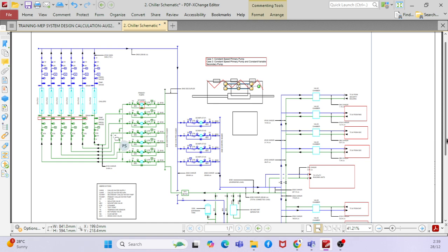Yeah. So then it will go to the chiller. That particular chiller will try to sense the flow, and whether the delta T can be maintained or not. If not, it will try to reduce the compressor speed to maintain the chiller flow rate and the chiller temperature. Still, if it can't, then what will happen? The chiller will go into switch off mode. Clear, right? Then the other chillers will be working to satisfy the building requirement, right? Okay. Understood.